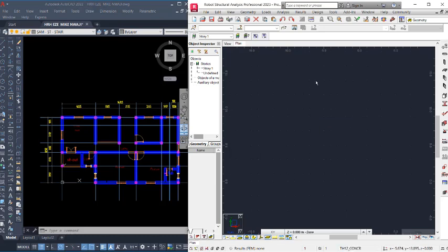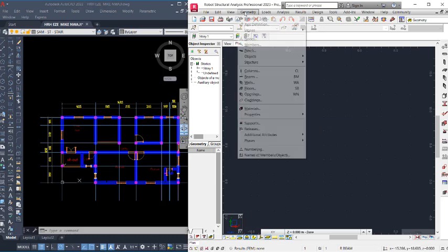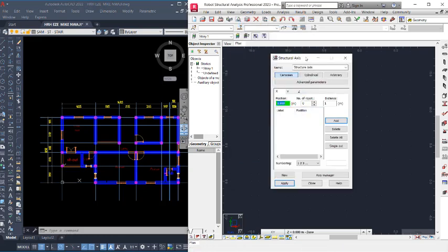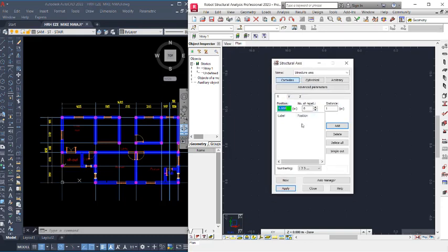So, let's navigate to the geometry tab, click on the axis definitions, and you will have the structural axis dialog just like this. On the plan, the horizontal dimensions are for the x axis and the vertical dimensions are for the y axis, and for the z option, it is the story height. Okay, so let's start the modeling.